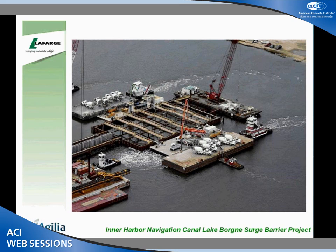Project, one of the massive gate structures in the city after Katrina. This project was 5,000 yards. This water is 27 feet deep. We're going to put a seal slab in there. So this cofferdam is only supported at the top. There's no horizontal bracing below grade at all. It's just driven in the mud.